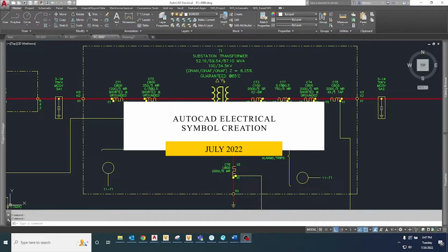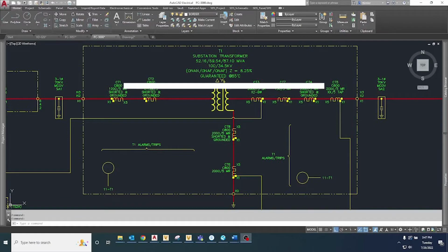Once you create a few symbols and discover that you can reuse attribute templates you've already arranged and pre-filled, you could use those to create different symbols across the same symbol family. And you could simply use basic AutoCAD commands to quickly build out the rest of your library. As you build out one-line symbols, for example, you'll probably want to reuse the same attribute templates for the three-line symbol counterparts. Just copy your AutoCAD geometry to a new drawing, copy your attribute template from your one line, add a few more connection points, and save the drawing. You'll save time as well.